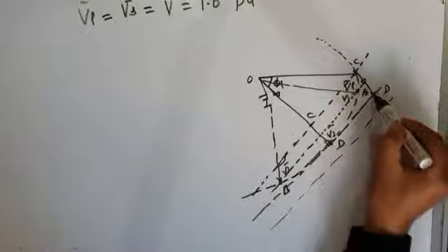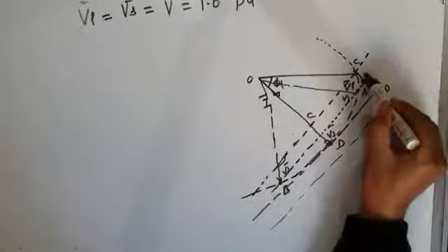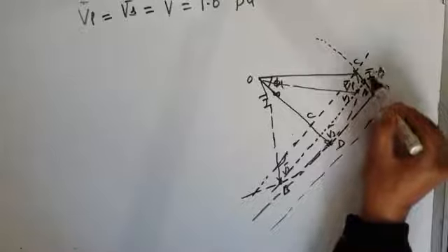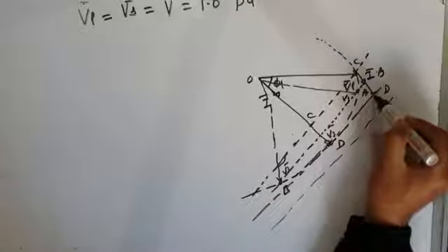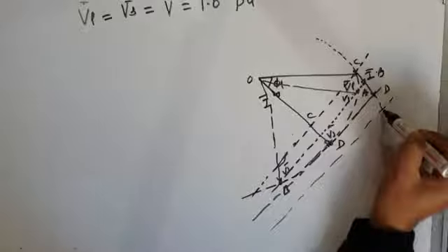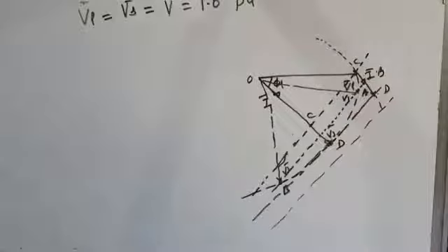This is the resistive voltage drop. This is I into RS. It can be either less than CD or at the most equal to CD. It should not be greater than CD for voltage regulation, for perfect compensation by DVR.